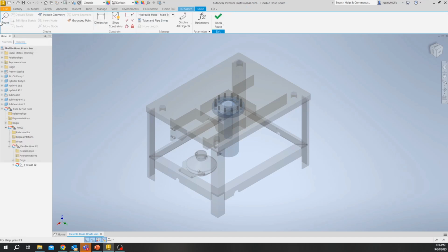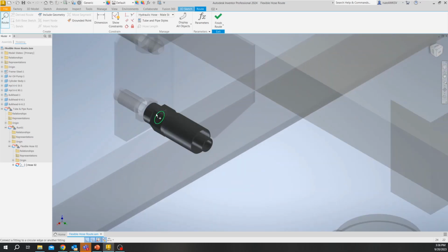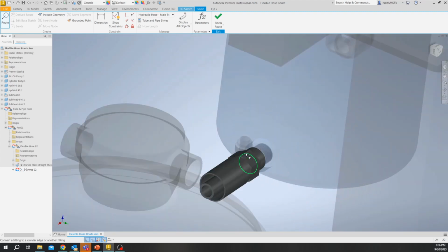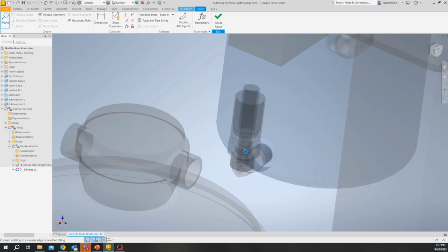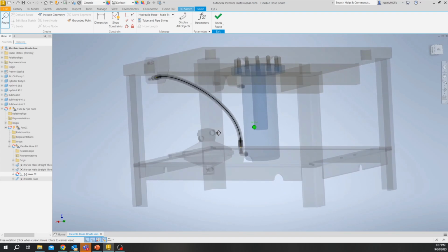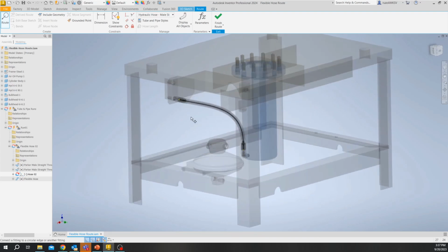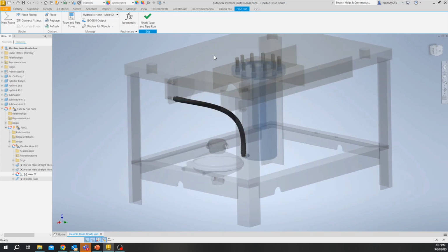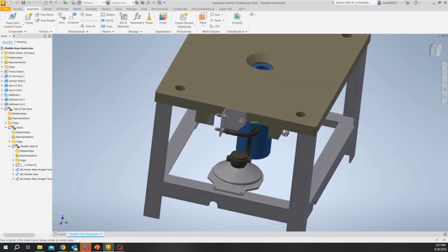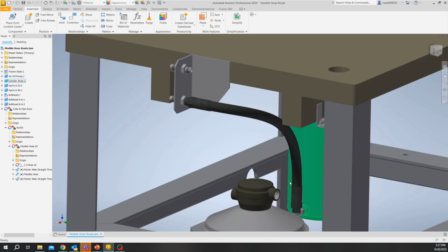and then we'll click New Route in the Route tab, and then we'll click Route in the Create tab, and I'll select my starting point, and then I'll be selecting my ending point. And as you can see, they are using connectors to determine your starting and ending point, and then if you selected your ending point, this will generate a flexible hose along the route between the 2 points that you chose. And if I click finish, now you can see that they brought the hose and the connectors into my model for me to visualize and share with the team.